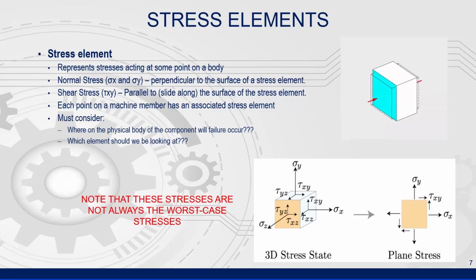The stress element represents a specific location on a machine member or body. Much like finite element analysis, we are looking at a specific element on our component at a location of interest. We generally use a cubic element as this facilitates easiest analysis in terms of a 3D coordinate system.